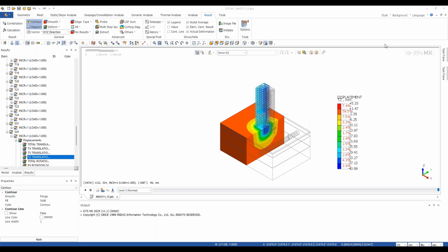Okay, once you excavate, let me show you. Okay, see, I'll just hide the soil layers. Okay, see the tunnel. Once you excavate this particular soil, if you don't provide any support, then there would be stress relaxation from all the sides. So in order to restrict that, we need to give support. Suppose I excavated this lane, see immediately the liner or the shield element is activated. So this is how you would do it. Okay, so this is the last question. I hope I have addressed your question.